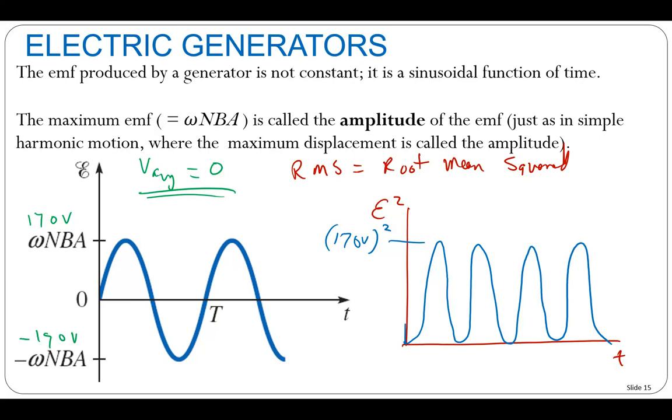What's the average of this sine wave? Yes. Now I'm just going to put V max. V max squared over 2, so it's generic. So the first thing I did was I squared it. That's why I showed you the graph. Then I did the mean. That's finding the average of the V squared.